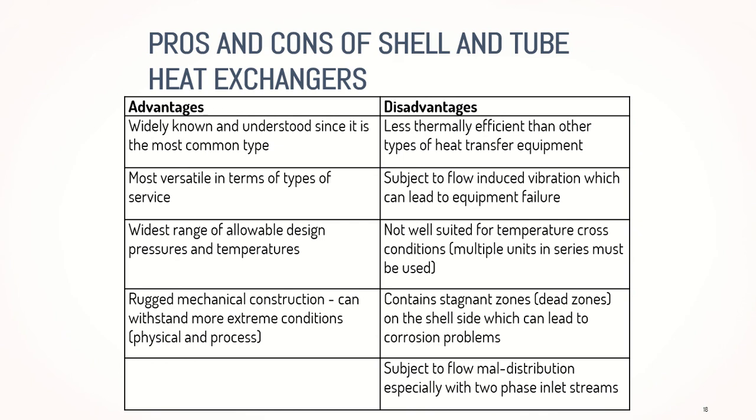So we have to ensure that the baffle pitch, the distance between each baffle, is optimum, to avoid the dead zone. And we also have to ensure that we don't use this type of shell and tube exchanger for two phase fluid.